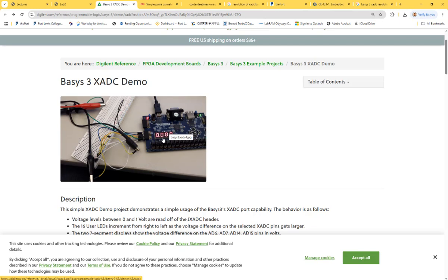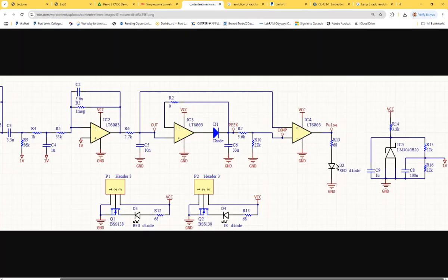That will be a pretty big change to our design. Eventually, the analog input cannot go beyond 1 volt. If we come back to our design here, remember we are setting up our DC offset at 1 volt, which means the AC signal is going to swing around 1 volt. That won't work. So I have to change this to 0.5 volts.